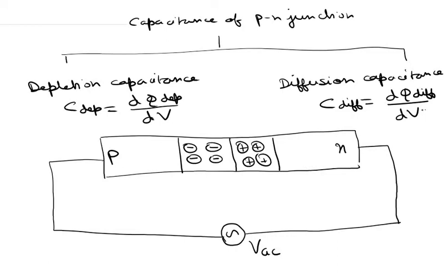Let us say that the voltage is varying very slowly, and so this depletion charge and this minority carrier concentration are getting enough time to actually adjust with the applied voltage. If the voltage is changing very slowly, the total depletion width and the charge due to the minority carriers are getting enough time to change in response to the applied voltage, then the diode behavior doesn't change much.